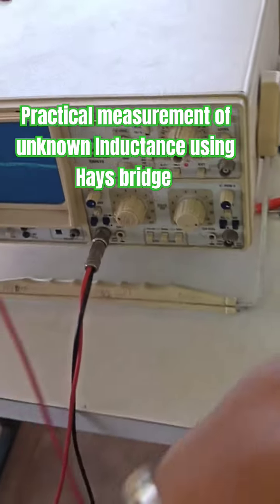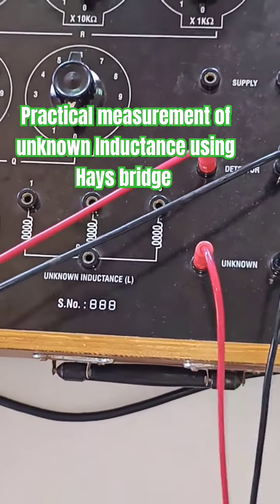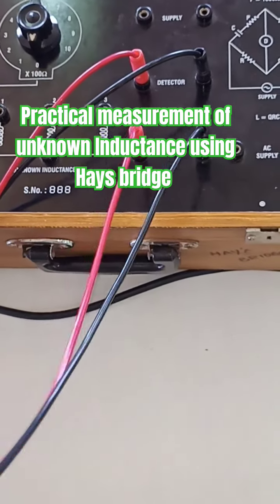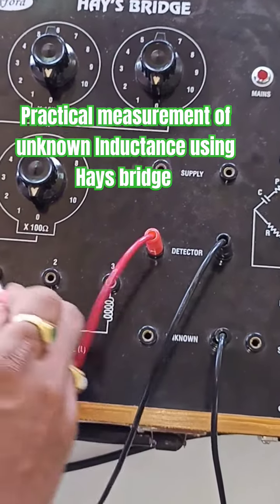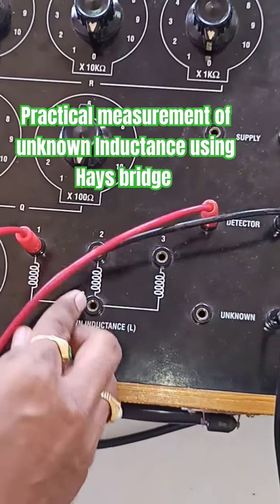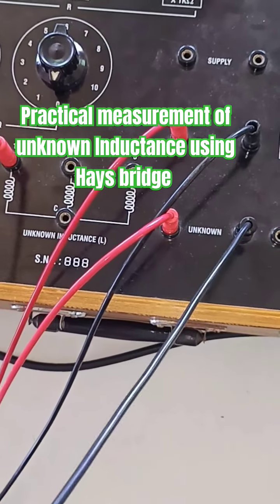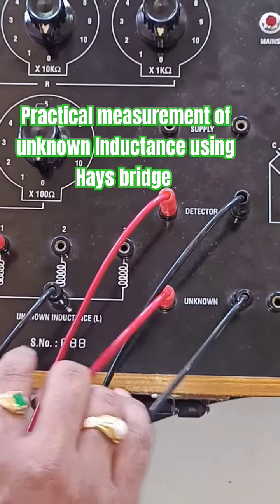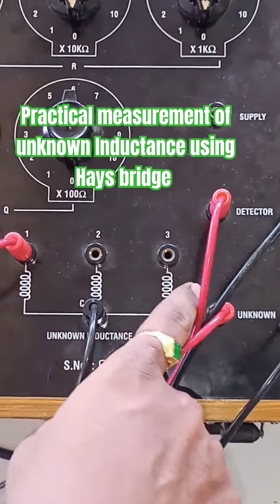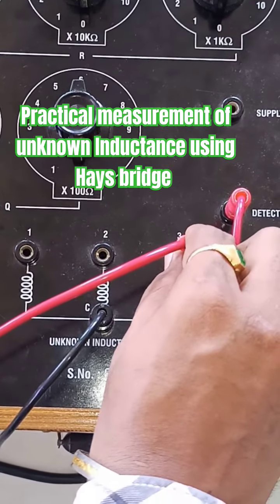So this detector we are connecting to the detector point, and this is the unknown inductance. Unknown inductance means we have to inject. So connect one terminal of the inductor to the unknown terminal, and the other terminal of the inductor you connect to this inductance. Here we can measure 3 unknown inductances, 1, 2, 3. Now I am keeping it in the third position to measure this unknown inductance.